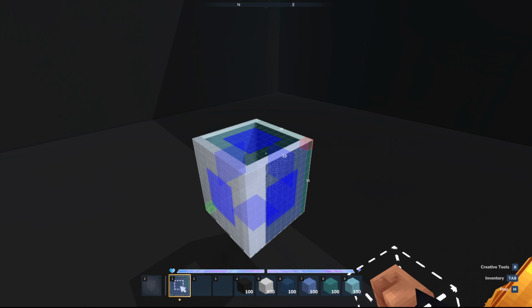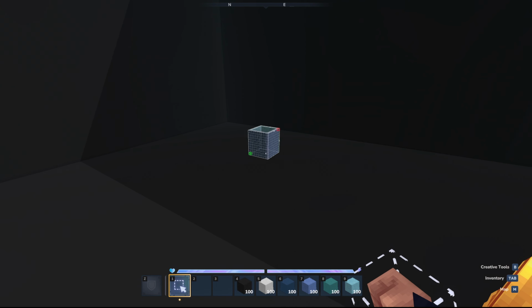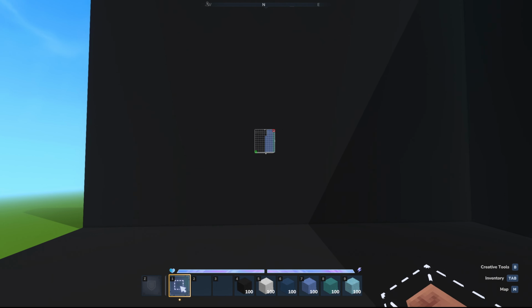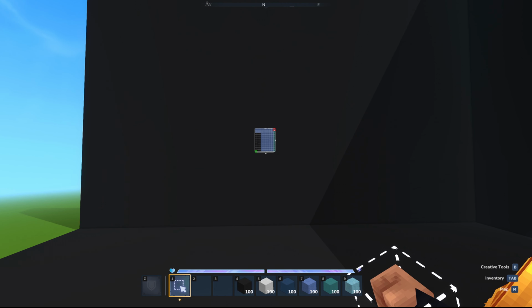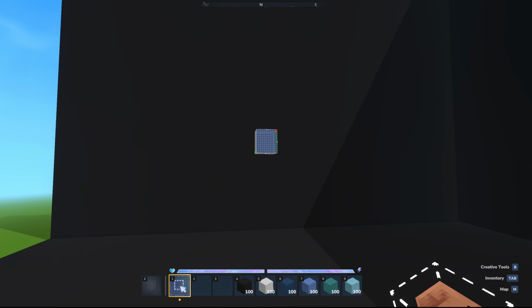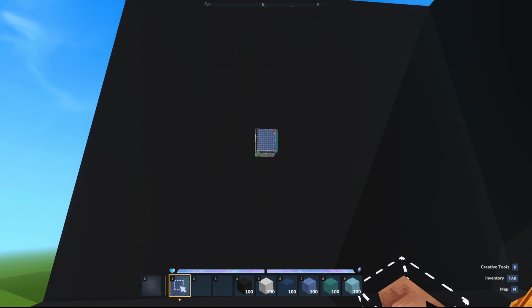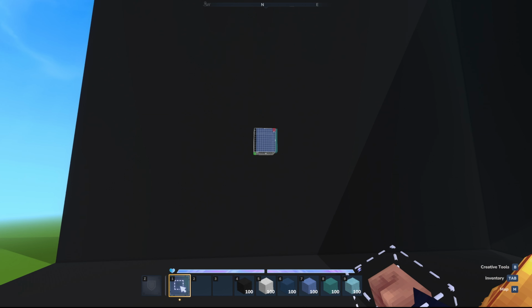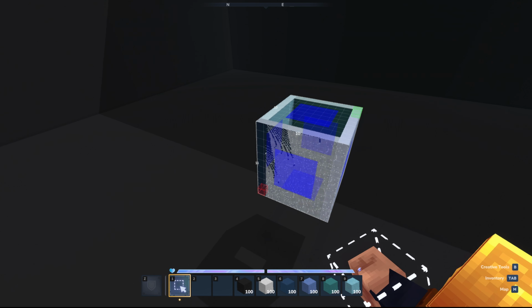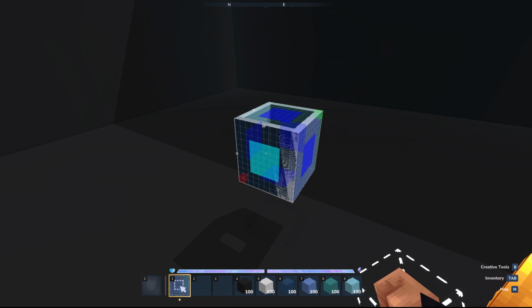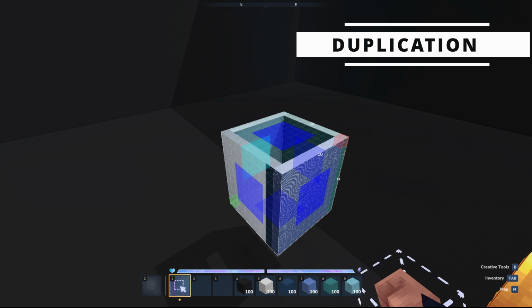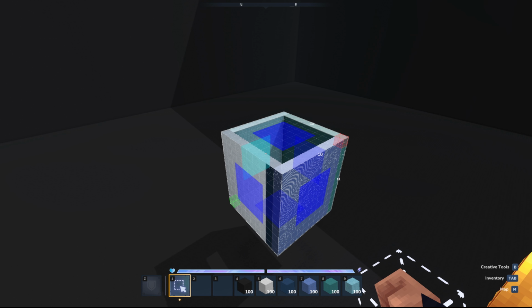Lastly, there's one more thing you can do. Let's say that you are in the middle of the selection, right? You haven't locked it in by pressing right click. What you can instead do is press X on your keyboard while you are in the middle of transforming, and that will automatically prevent your transformation from taking effect. There is seriously so much just the selection tool can do.